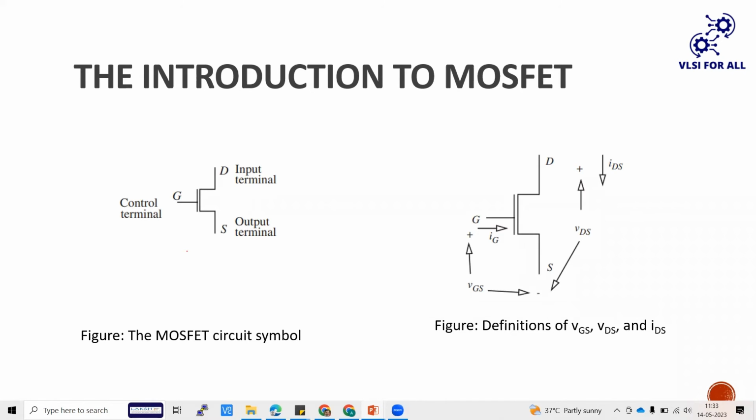Because the threshold voltage, you know from basic electronics, is the minimum voltage required to form the inversion layer between the source and drain. Therefore, the charge carriers move from source to drain through the inversion layer. If the charge carriers are moving, obviously you get the current. So the required condition to become on is none other than simply that the input voltage VGS must be greater than VT. That's it. Now you can see the VI characteristics as well.